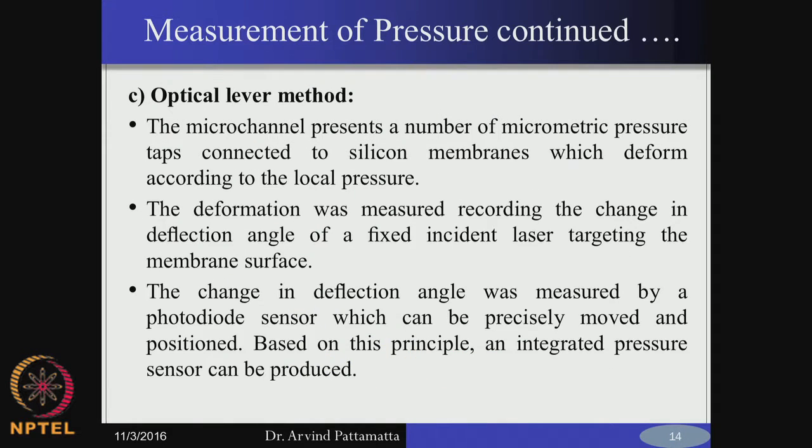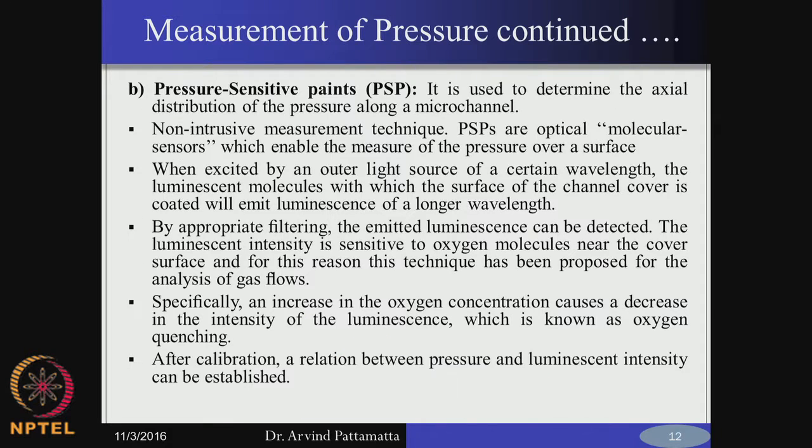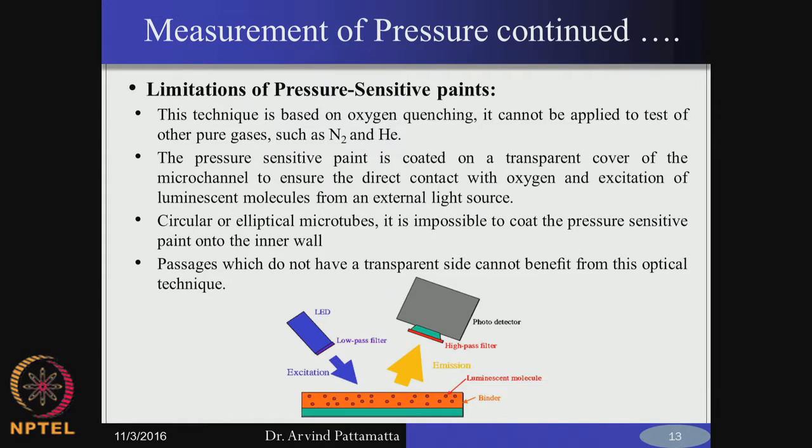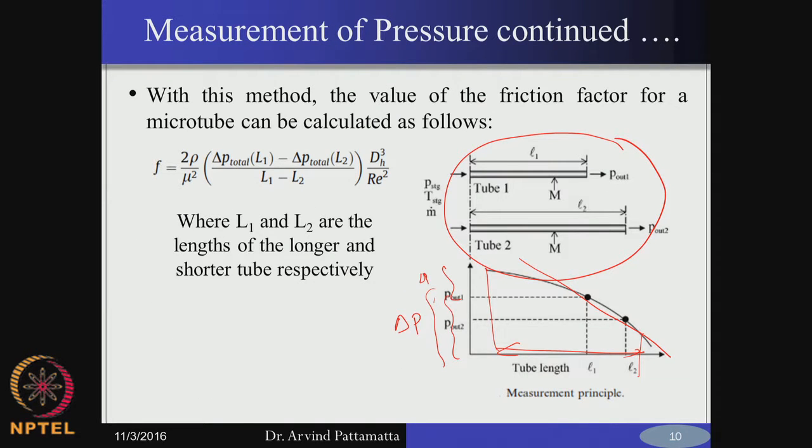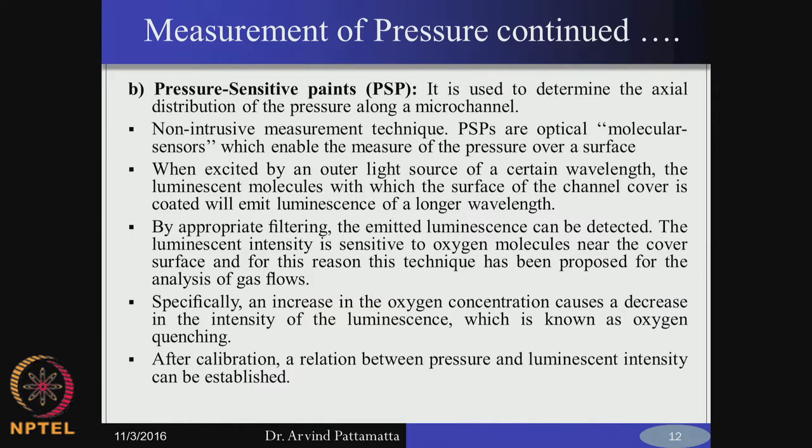So, the other technique, one such technique, is called pressure sensitive paint. This is not so commonly used in our institute, for example, and this also requires highly sophisticated equipment compared to a simple differential pressure transmitter in the earlier case. In the case of pressure sensitive paint, we rely on applying a coating, which are like molecular